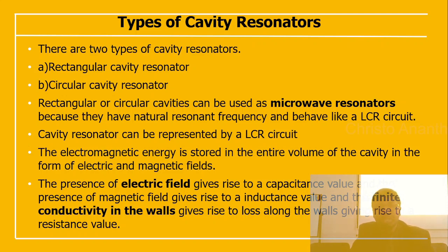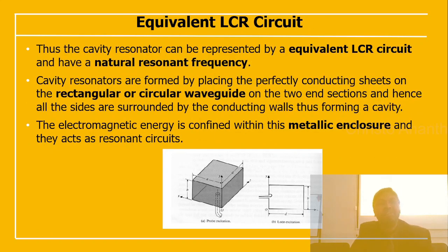The presence of the electric field gives rise to the capacitance value, and the magnetic field gives rise to the inductance value. There is also finite conductivity in the walls, which gives rise to losses, and across the walls that gives rise to the resistance value. So the cavity resonator behaves as an equivalent LCR circuit and has a natural resonant frequency.